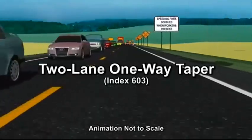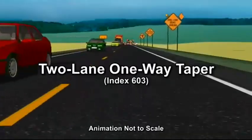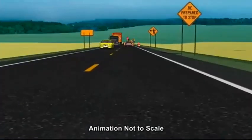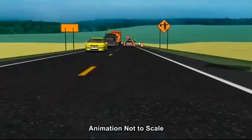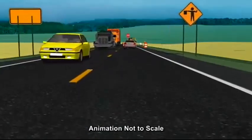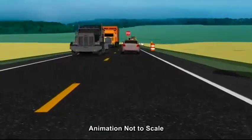Two-way one-lane tapers control two-way traffic where drivers are required to alternately use a single lane. These tapers are used when flaggers are present. A short 50-foot taper is used to slow down traffic by giving the appearance of a restricted alignment. One or more flaggers or temporary traffic signals are used to assign the right-of-way in such conditions.